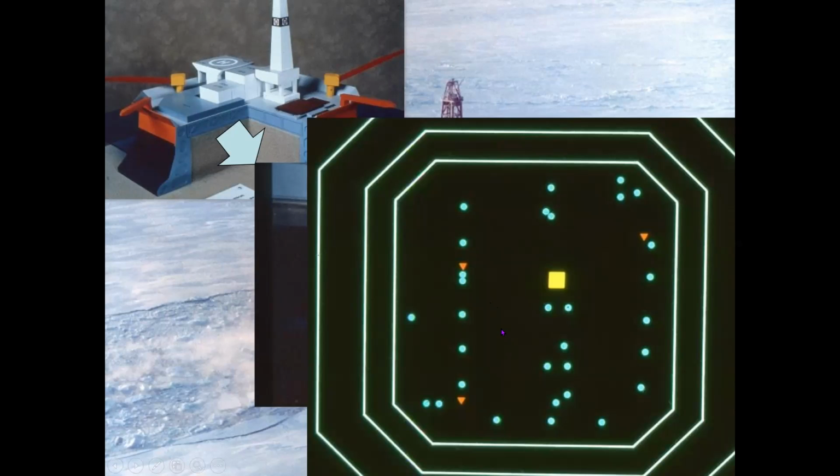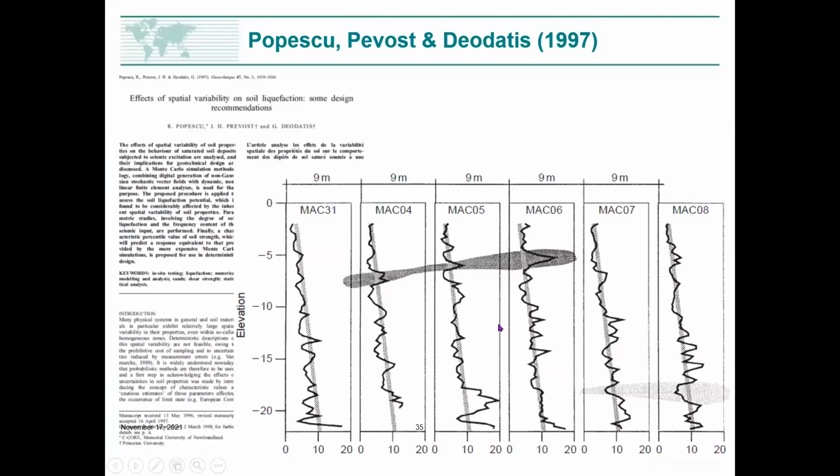What you can do with that level of CPTs, you can actually start seeing dense zones and how continuous they are. And to see that, we actually had to bring the spacing down, as you can see, to 9 meters. And you can see down here a loose pocket. As I was pulling the slide together, I thought, actually I might have brought the loose pocket over to here.